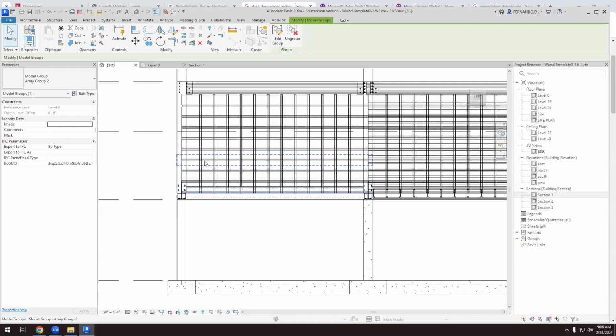Now that we have something structural, if we don't do this, we can cut structural elements or we can create another frame, but it will be more expensive. Once we have made up the grid, the distance between vertical and horizontal elements, make the most of that, because if you don't, it will be more expensive, and we will need other structural elements. If we already have structural elements, why do we need to add more?